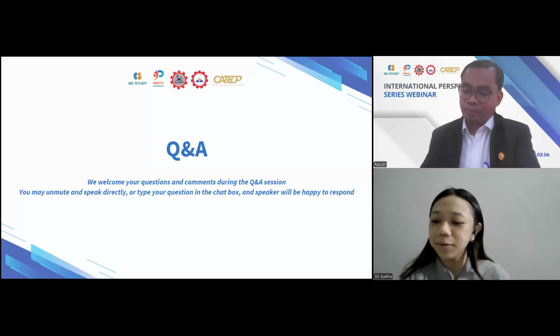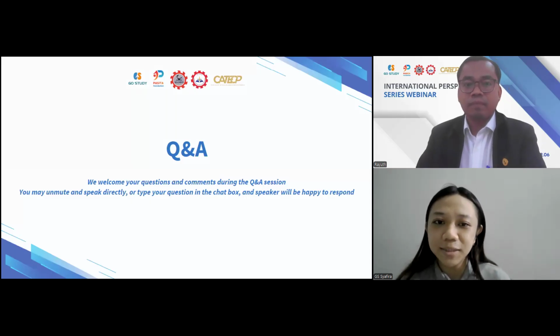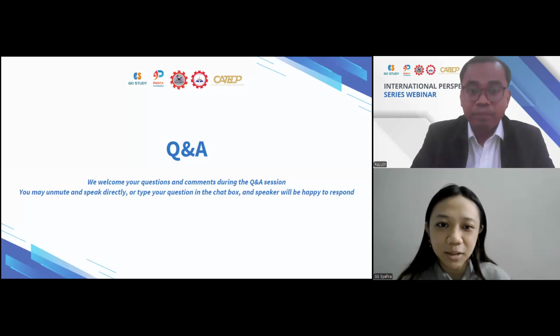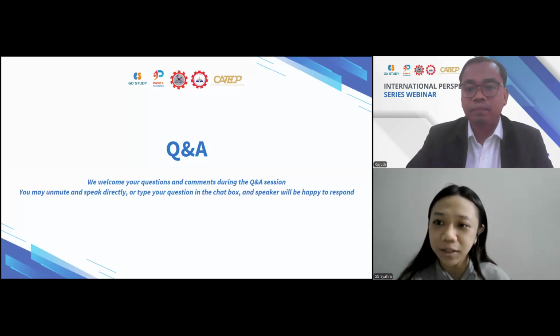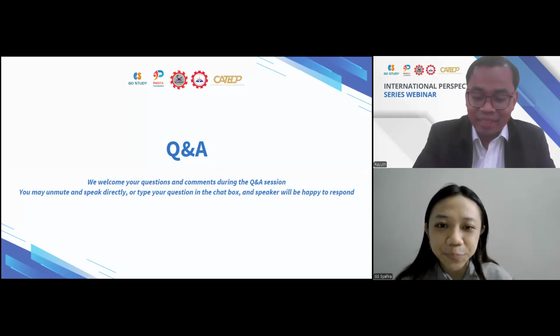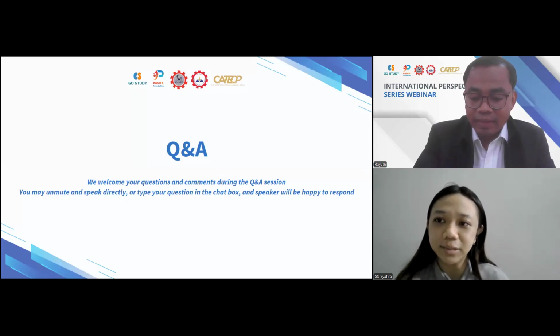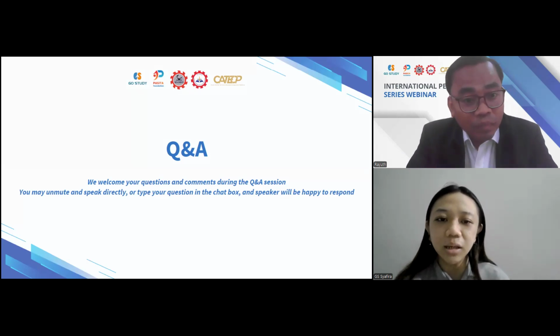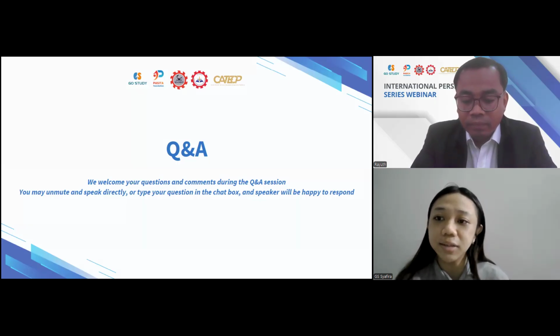Okay, so we will now start the Q&A session as I have seen a few questions here. Maybe we can start with a question from David. It's a very long question, but it's okay. From practical simulation experience, thermal bridging cannot be treated through average or effective thermal properties. It has to be modeled explicitly as a real high-conductivity solid path in 2D or 3D, because heat always finds and short-circuits through studs, fasteners, and frames.